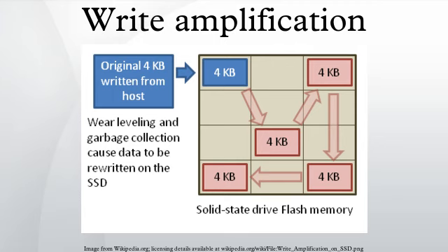Wear leveling. If a particular block was programmed and erased repeatedly without writing to any other blocks, that block would wear out before all the other blocks, thereby prematurely ending the life of the SSD. For this reason, SSD controllers use a technique called wear leveling to distribute writes as evenly as possible across all the flash blocks in the SSD. In a perfect scenario, this would enable every block to be written to its maximum life so they all fail